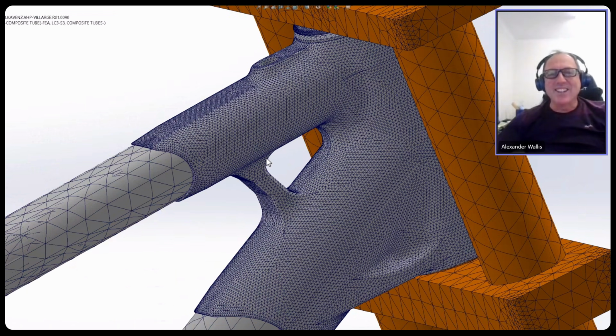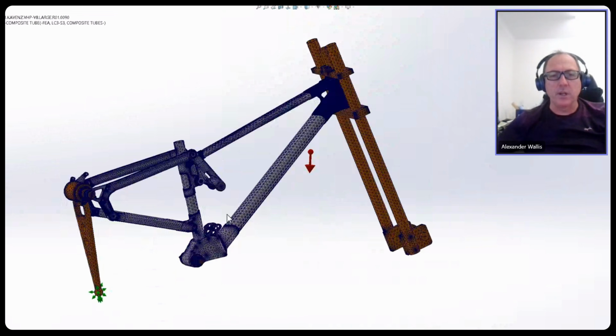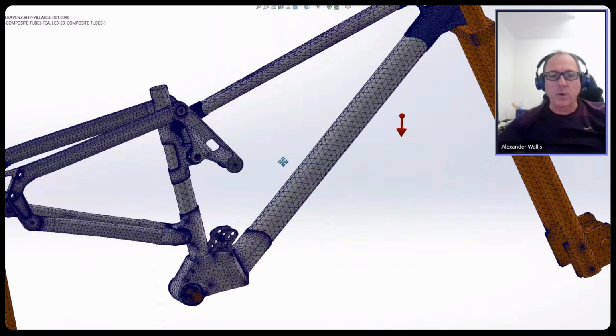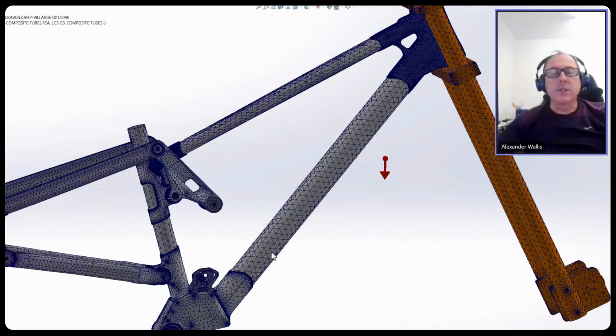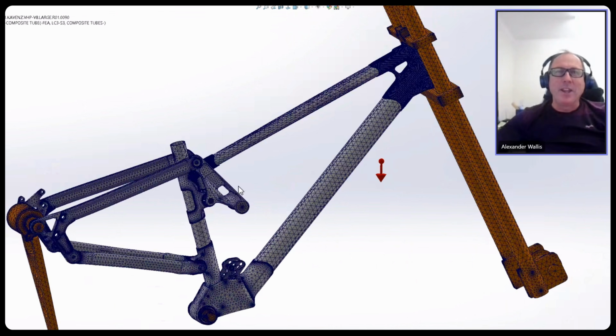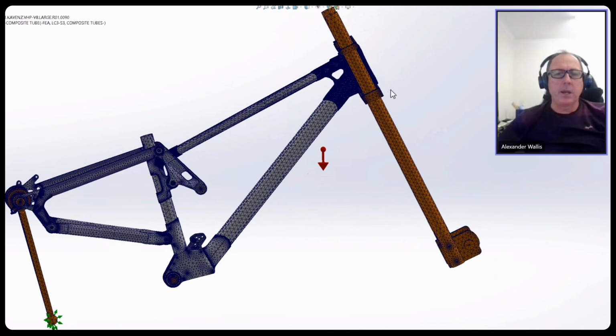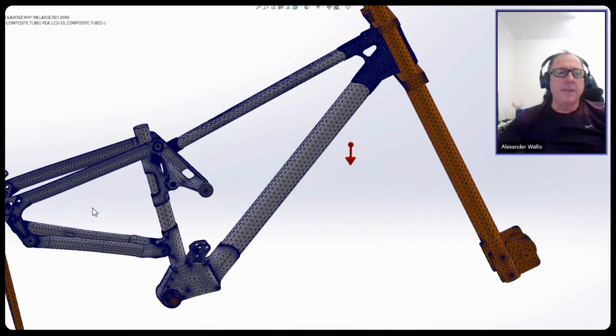Nowadays on a computer, this one here for this type of mesh is running around about 3.5 to 4 hours. On this very high resolution mesh, which we've got a couple of runs on, we've got results running in the background. They are around 6-hour calculations, and these are double CPU computers with 2 processors and lots of memory. We do this inside the CAD programs. We can bring it straight into something like SolidWorks Simulation, and we also use another simulator called Abaqus to do these calculations. The output from these, obviously, is we work out every bit of deflection.